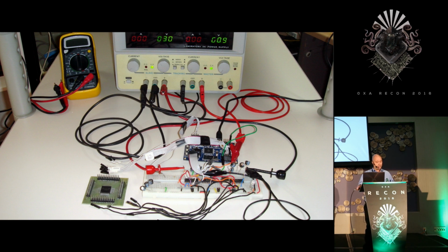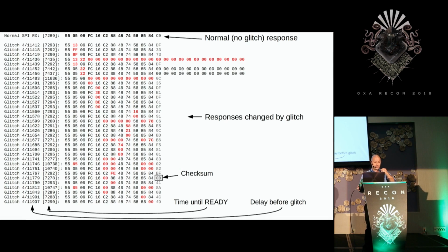So this simple breadboard-based glitcher was very flexible. The breadboard can be modified to test different ideas and can be reconfigured quickly, and I didn't really need to make anything more advanced than this. So to test if the glitcher will work, and to find what voltage levels to set it to, we can send a command to the ACP, then glitch, and see if the response is unusual.